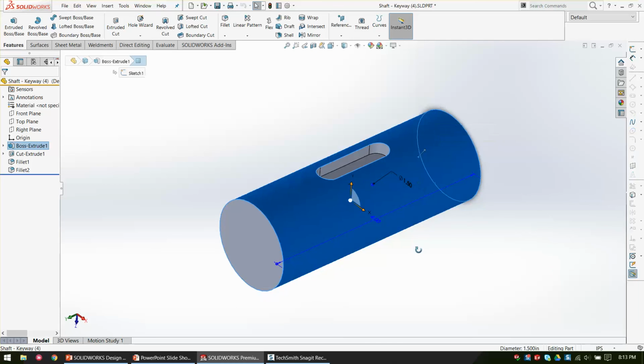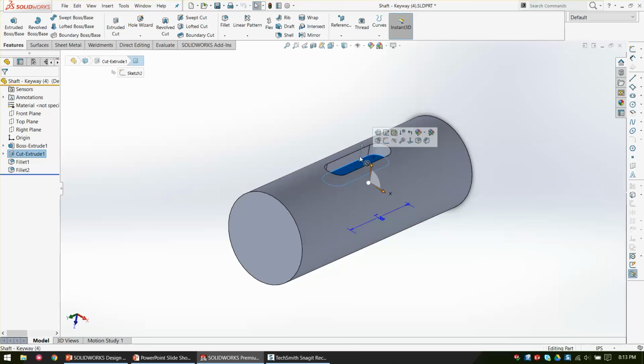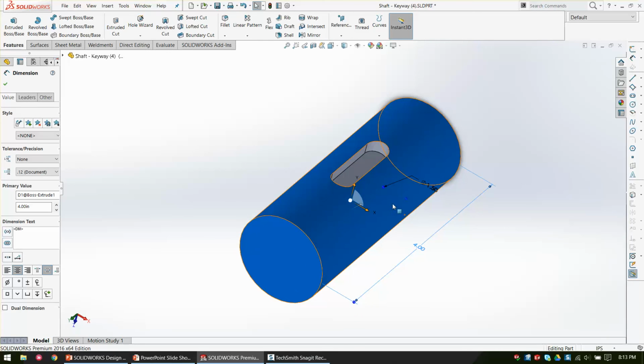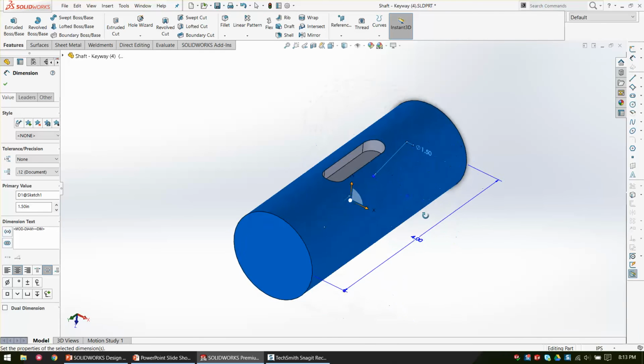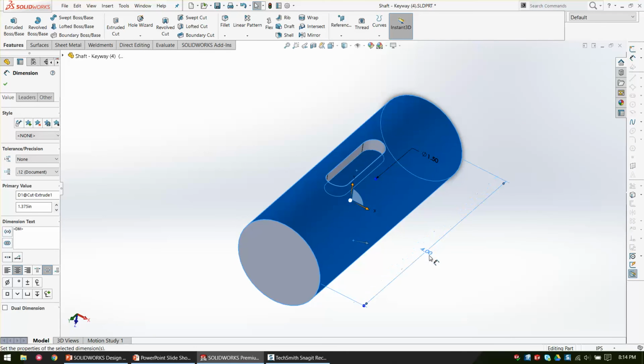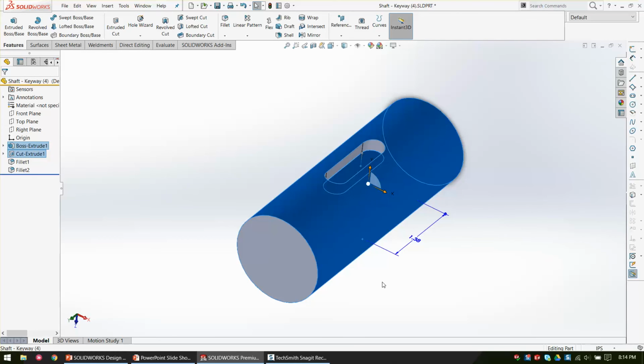with two fillets. So we have here literally, and I've got to turn off Instant3D, we literally have here, if I can find them all, there's a dimension hidden there, but there's three dimensions for this part. There's the shaft diameter, the shaft length, and how far of a keyway I want, 1 3/8 in this instance. There we go. Now they're all showing, sort of. Well, I think it's a graphics problem. Anyway, but three dimensions. You cannot pull this off with three dimensions in any other way.